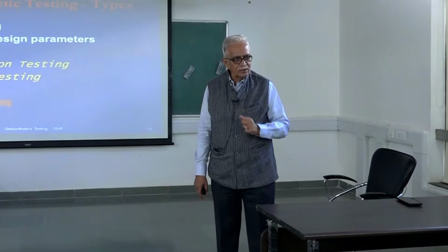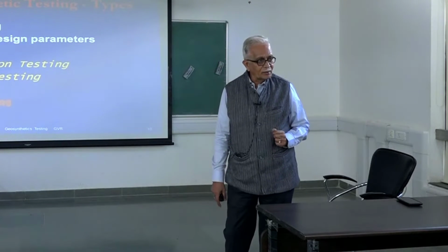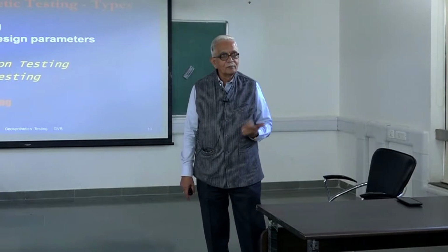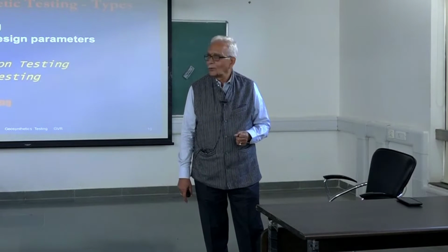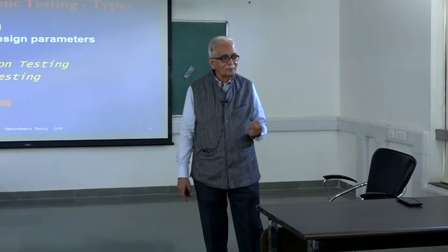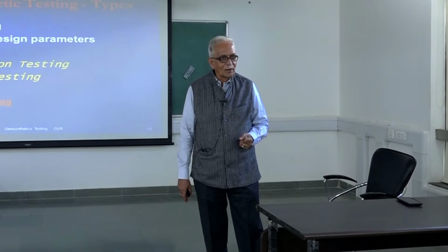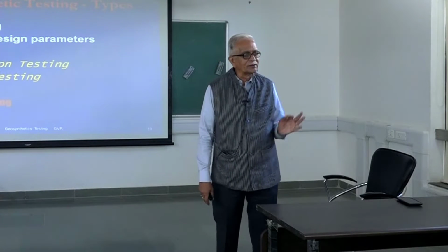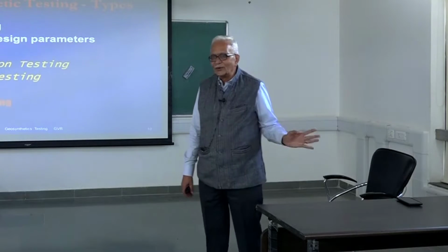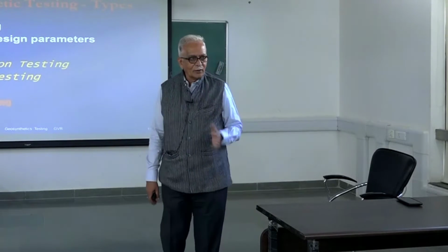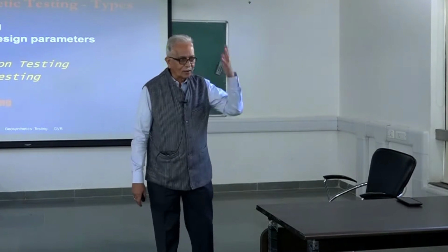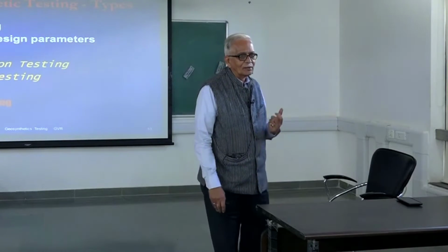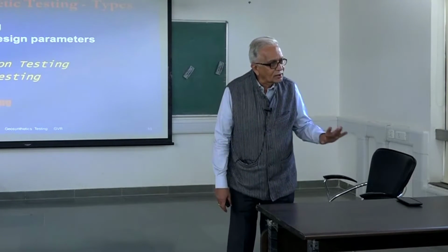Is there a test actually in civil engineering which we do at 300 per minute? No? Have you done any bitumen testing any time? In mix design, the Marshall test is done actually at that speed. No other test do we do at that speed. Okay, we also specify the kind of machine, not that I am going to use a Marshall machine for this now. The point is that we do not do normal testing at that kind of speed.